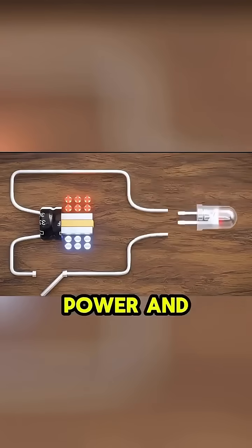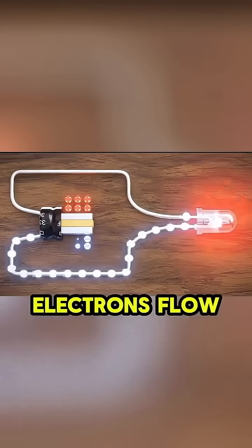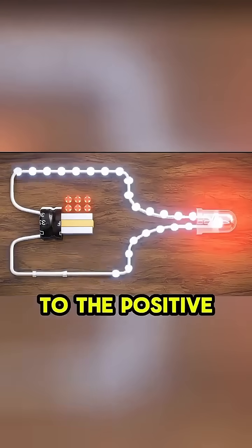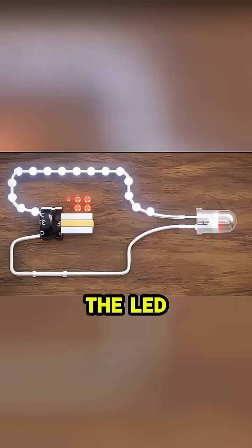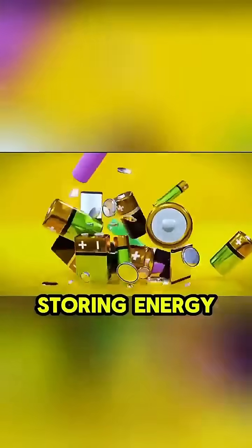Now we'll disconnect the power and connect a load, like an LED. Due to the potential difference, electrons flow from the negative plate to the positive. As a result, the LED lights up. This is one of a capacitor's basic functions, storing energy.